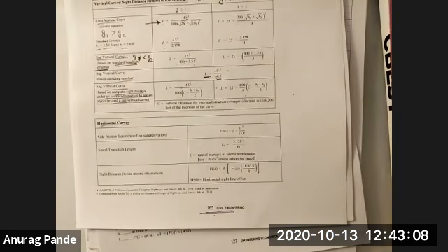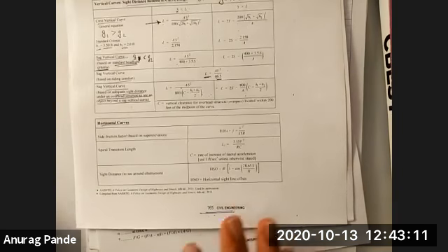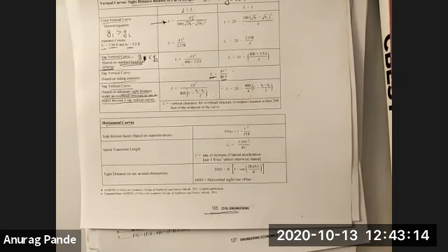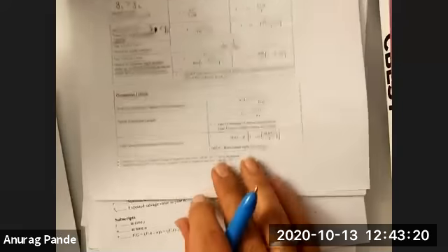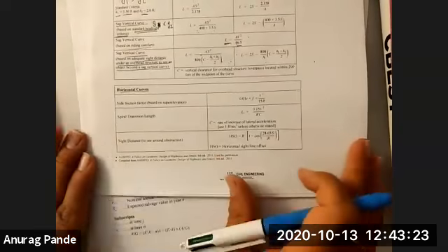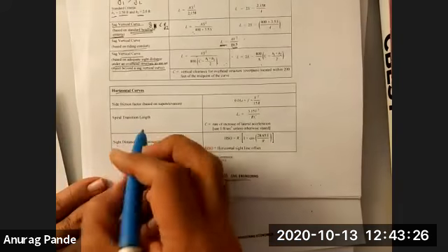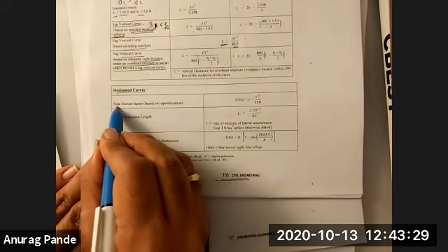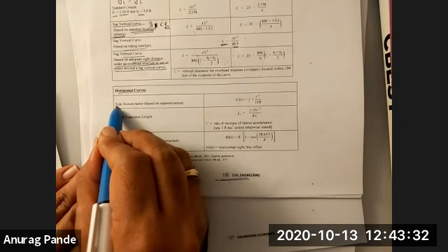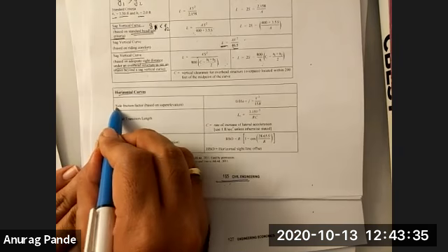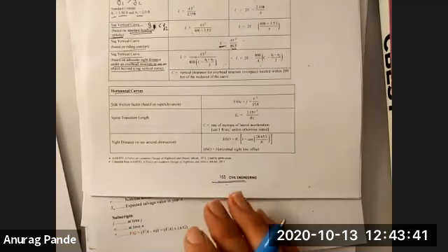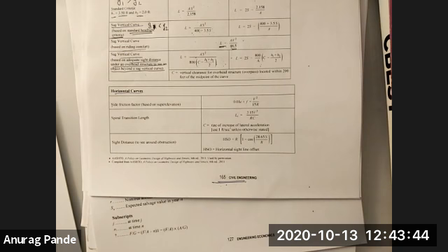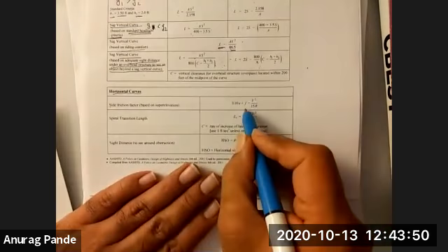Now, for horizontal curves, things are slightly different. There's a lot going on in a horizontal curve. You look at it from the top view perspective, and those formulas are given here. There are things here that you need to worry about. For a horizontal curve, there is the idea of the side friction factor. That is different from the longitudinal friction factor that I talked about at the very beginning when we were talking about the stopping sight distance formula. The side friction factor is about the sideways movement, the lateral movement, okay? And then this is basically the superelevation calculation.